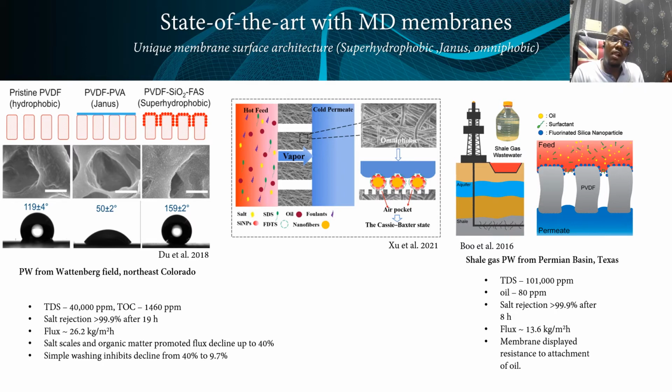Hollow fibers have also been put forward as a better option due to their ability to fit in small spaces, ease of cleaning during clean operations, and basically no need for any spacers, as compared to the flat sheet membrane. However, they also have the disadvantage of ease of breakage, either during the cleaning operations or even when preparing the modules. But by and large, hollow fibers and polymeric membranes are favored in water and wastewater treatment and membrane distillation, particularly.